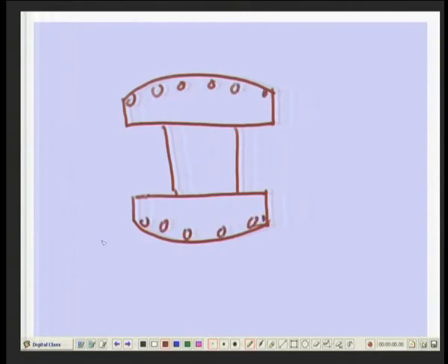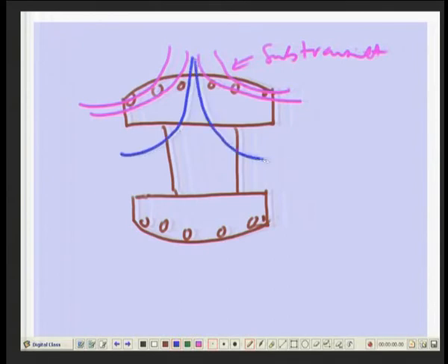okay, and the flux will go like this, because dampers will oppose. This is a subtransient flux, right. Then after some time damper gets tired and it will be 0 current, right. Then the flux will start penetrating like this. This is transient flux.